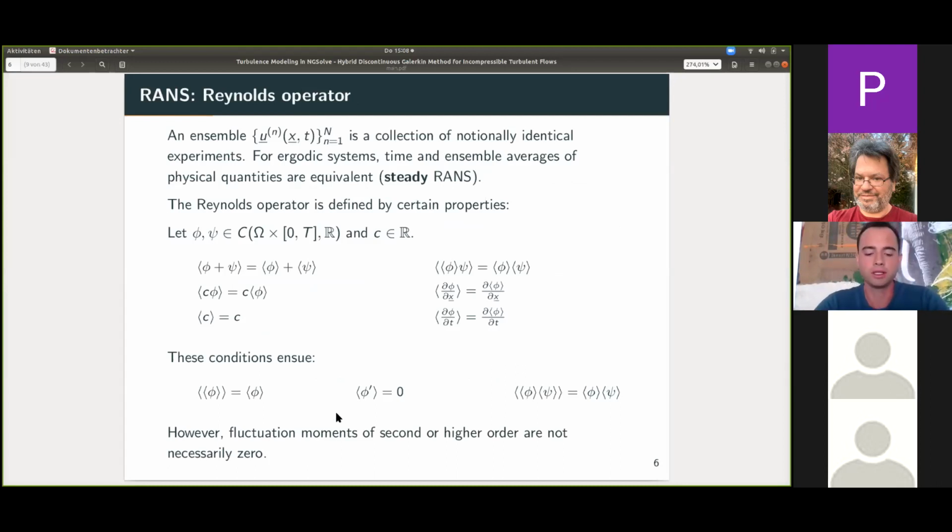Since the flow is turbulent, each fluid motion differs, and this has some historical aspects behind it, because if you repeat an experiment and some small differences happen in the experiment setup, this will become very significant as time progresses. So we have a completely different flow regime after time progresses. So an ensemble average would be the average of all those identical experiments.